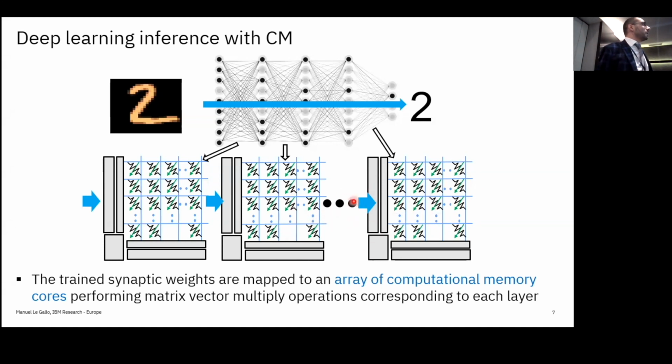Typically, the way we manage to do training with this is to have a digital accumulation of the gradients, and once they reach a threshold, you send some blind pulses to the device to increase the weights. Since the gradients are accumulated and computed in digital, backprop will take care of any error that happens when we update the weights, and then everything will work fine.